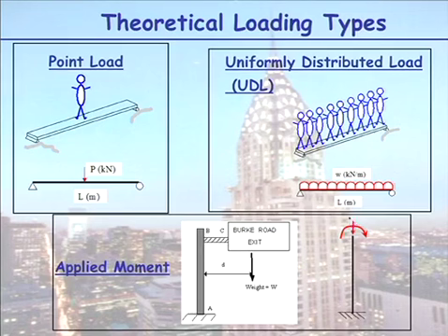So, last week I told you that we idealise our loading in three ways, either as a point load, a uniformly distributed load, or a blanket load. If we were working in 3D, then our loading would be applied everywhere, and that would be a load in terms of kilonewton per metre squared. But generally with this subject, we're dealing in 2 dimensions. So we'll work in kilonewtons per metre, kilonewtons, or an applied moment. And remember, the units of moment here are kilonewton metres, force times distance.